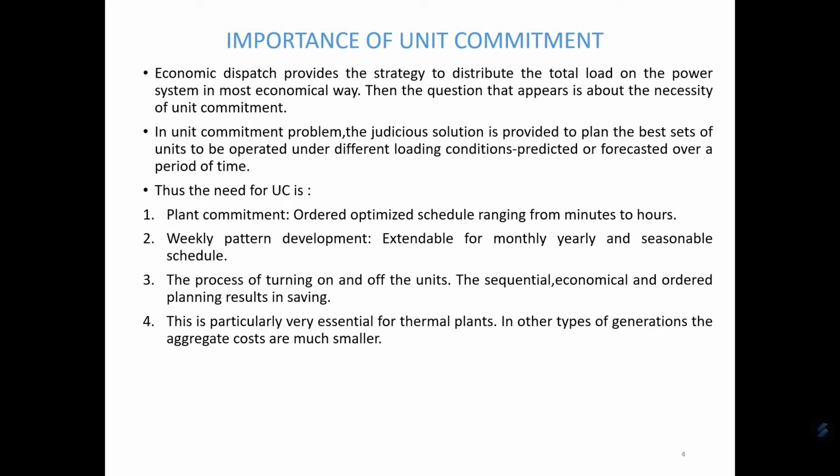Plan the base set of units to be operated under different loading conditions, predicted or forecasted over a period of time. So the need of unit commitment is planned commitment, that is, an ordered optimized schedule ranging from minutes to hours. Then for weekly pattern development, unit commitment is necessary. Then the process of turning units on and off, that is the sequential, economical and ordered planning, results in saving. And this unit commitment is particularly essential for thermal plants. In other types of generation, the start-up costs are much smaller.